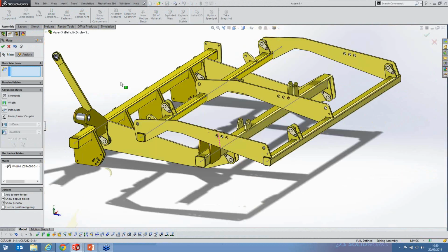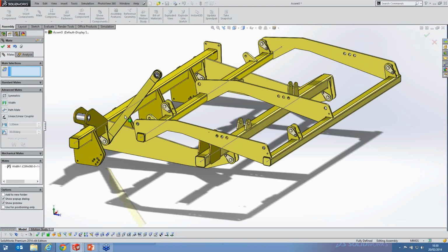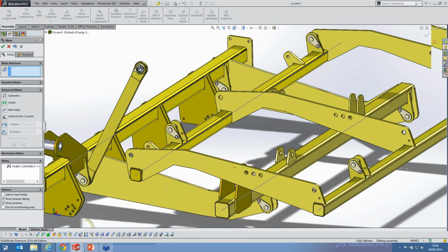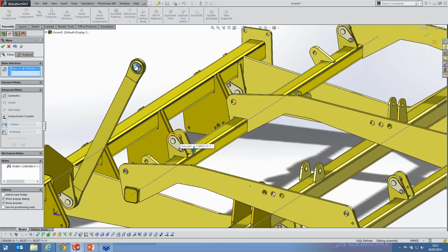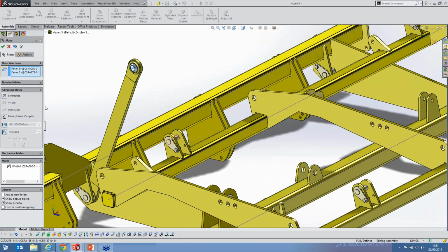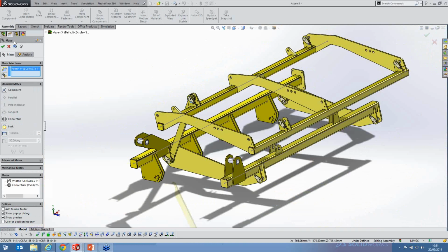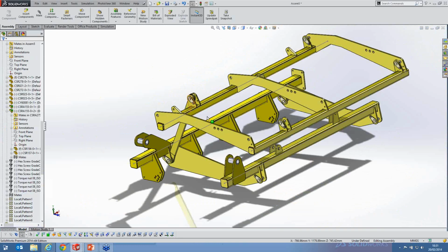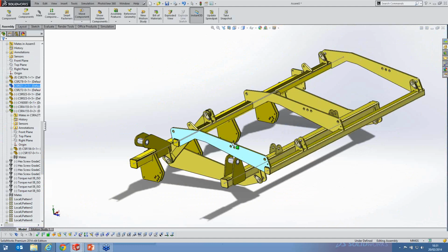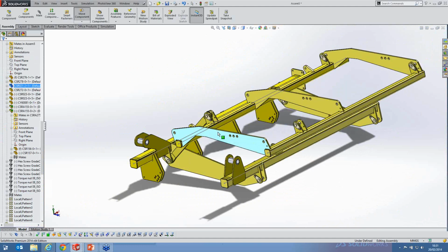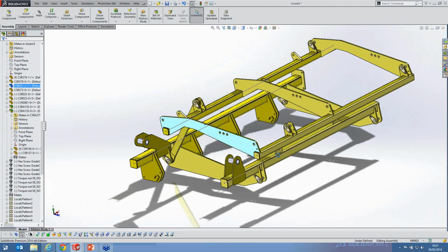You can see here how we can actually allow movement as well. So we've reduced some degrees of freedom for that component, but we've still got a rotational degree of freedom left. So we would now want to link that to there with a concentric mate, and now what we'll see is we can actually just come out of the mate tool there. We can actually move that up and down like so. So you can start to build up live mechanisms using this mate functionality.